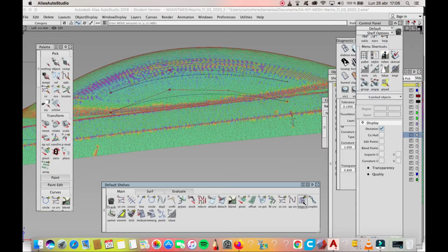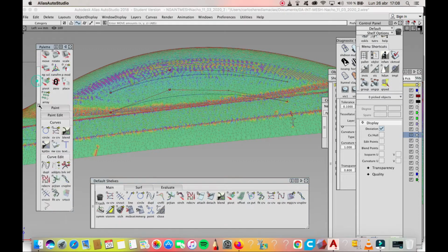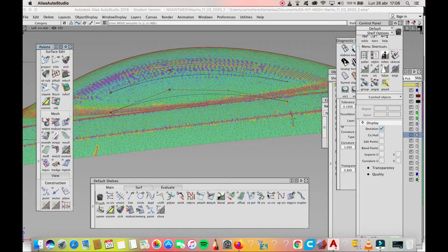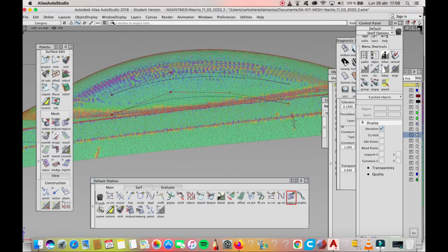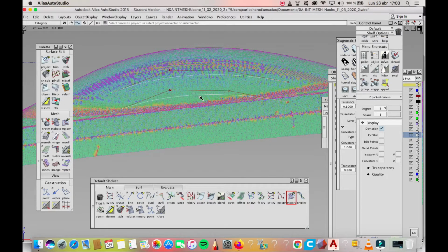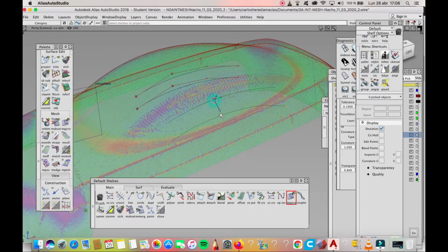So this is another projection tool. It's not the normal regular projection tool. This directly projects curves onto mesh, and you will find this tool under the mesh palette here. So I already have it in the shelf, so I'm gonna click it and select the mesh to project onto, spacebar, and then select these two curves and project into the mesh in the view that we are in. Okay, so what we get is this.